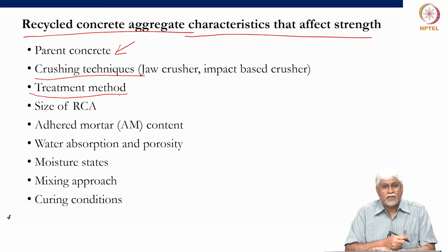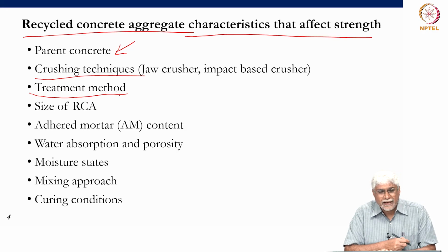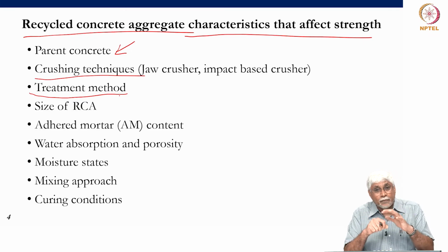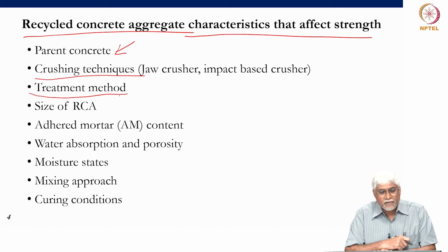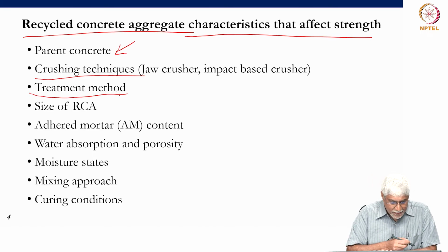Again, with the intention of removing the adhered mortar, making sure that all weak material is removed from the waste concrete when we are making it into aggregates, or making sure that the adhered mortar doesn't absorb water through some coating or some way to block, improve the bond. If we use such techniques, these are called treatments.